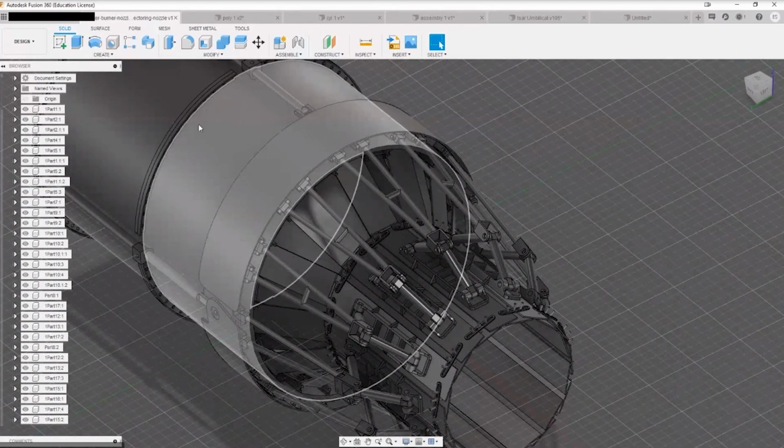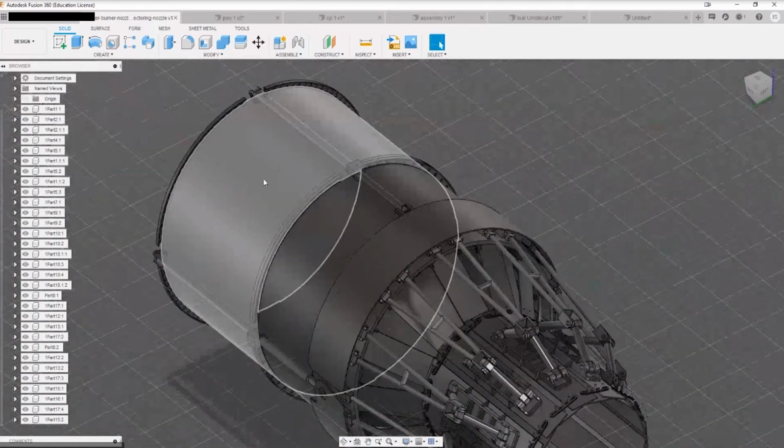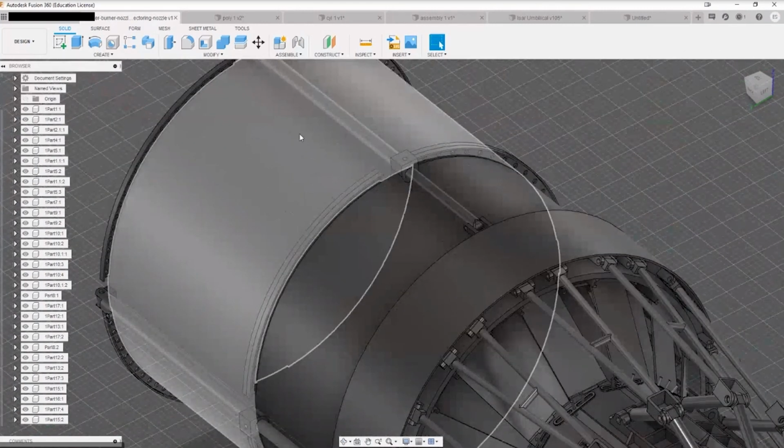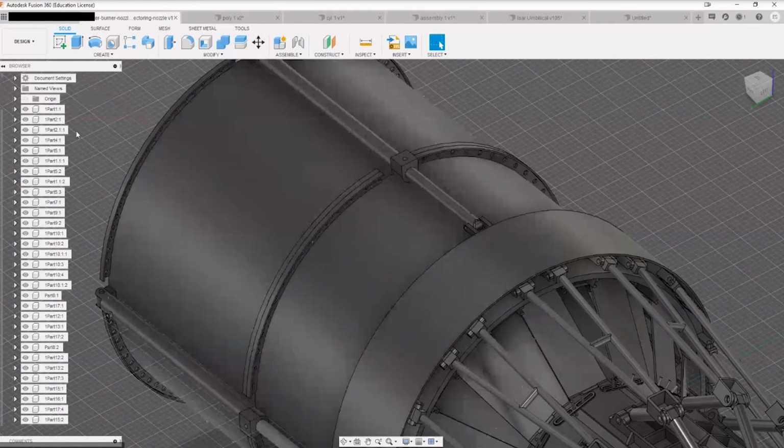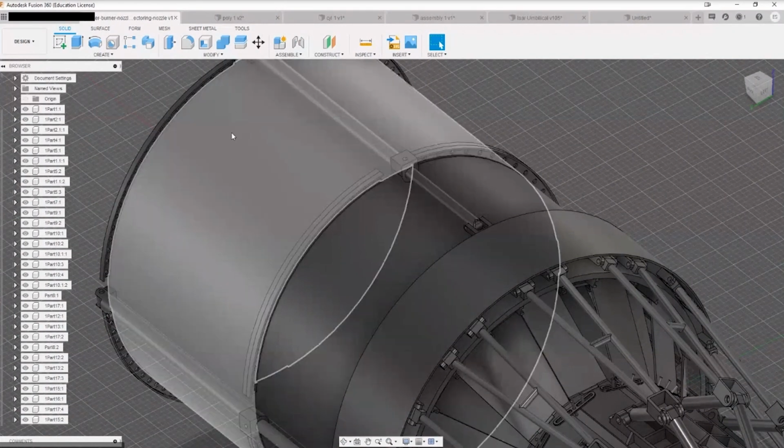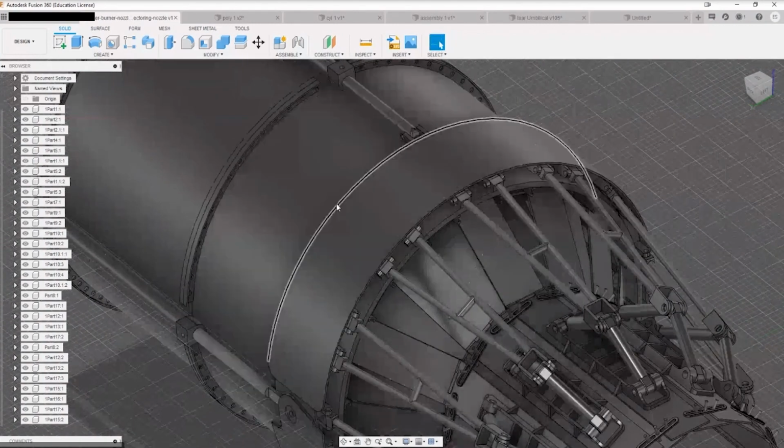For example, if I wanted to create an instrument panel that's curved and conformal to this location, I would tell the designer, if you've got a pipe or surface that has this radius, design for it. They would design it, and you would orient that component and fix it in place using some of the joints into this design. Later in the original component file, you can alter that however, and it'll constantly keep updating in the assembly file.